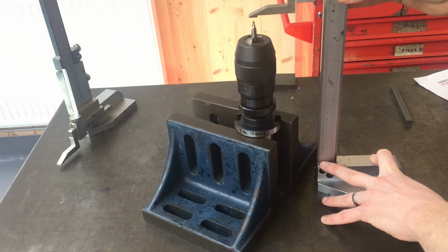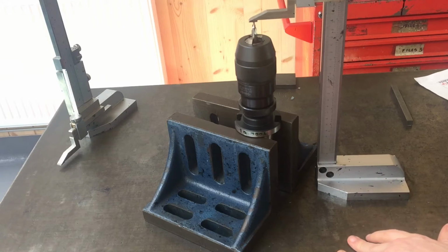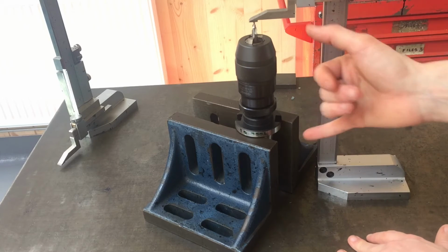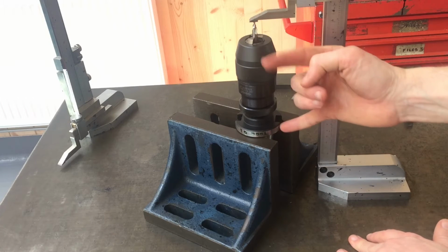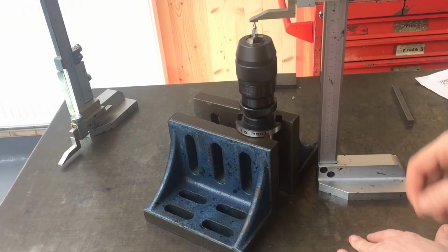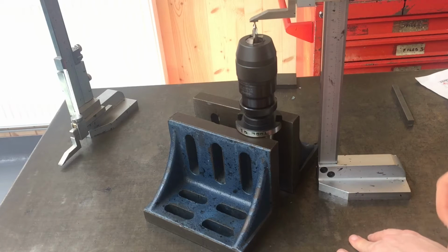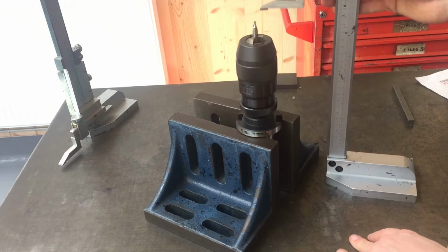and then take a measurement of the tip. So by taking those two values away, you're going to get the distance from the spindle nose to the end of the tip. So in this case, I've pre-measured that, and we now need to enter it into the control, and we need to put it into HSM Works.